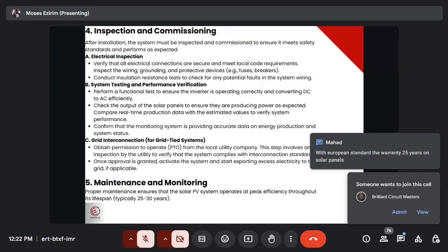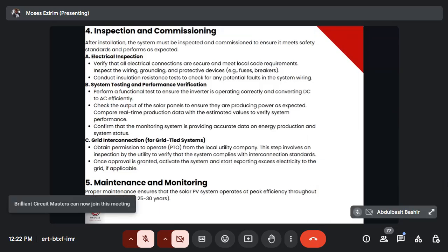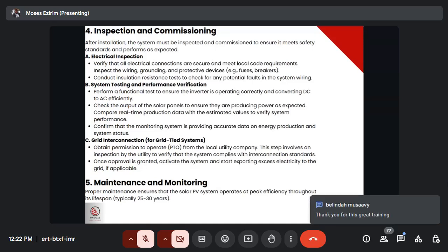A solar gets its reference voltage from the generator. Yes, so that means once the generator disconnects, there is no more reference voltage, and then your solar will go off. Can you buttress more on the system not yielding when there is solar? I think I've explained that, but you get to know more than when we do PV diesel.